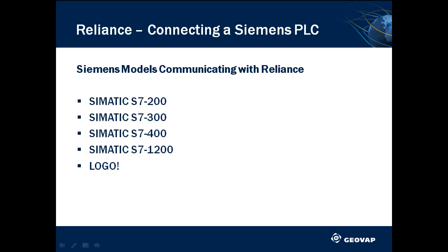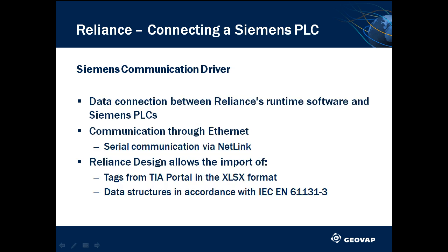Currently, Reliance can communicate with these Siemens PLC models: SIMATIC S7200, S7300, S7400, S71200 and Logo. The Siemens Communication Driver is intended to connect Reliance's runtime software to Siemens control systems via Ethernet, or a Netlink converter can be used for serial communication.